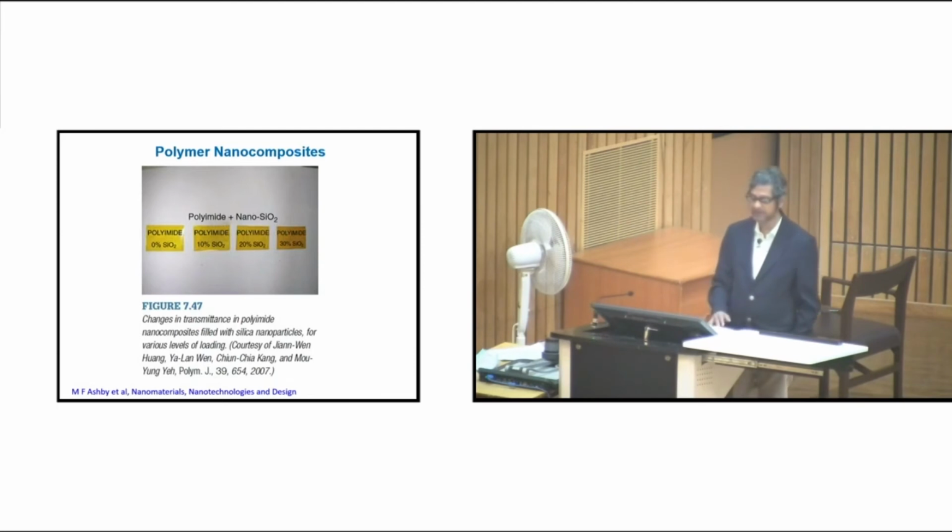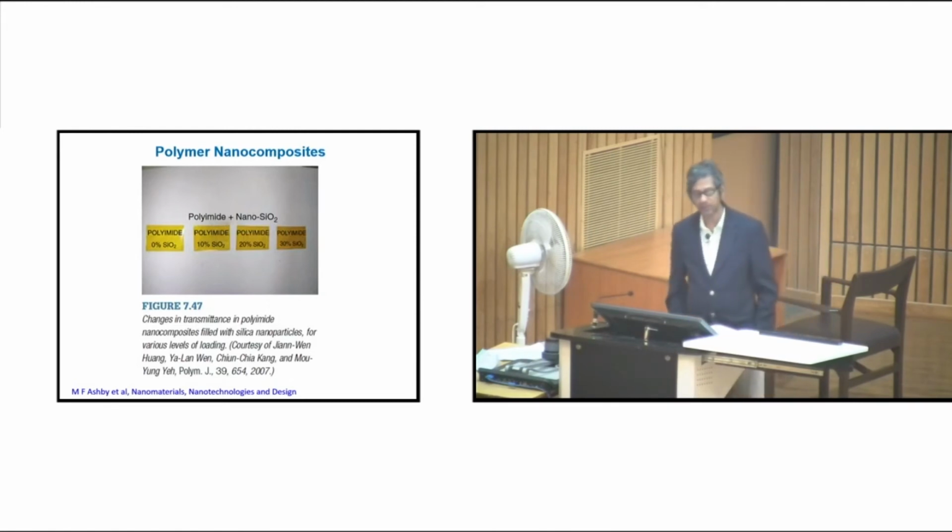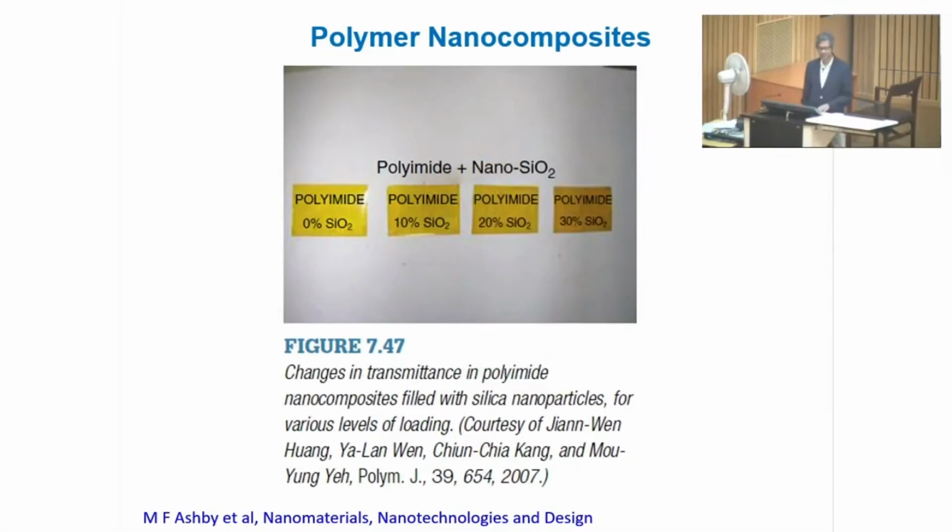To achieve transparency, the scattering must be minimized, which means the nanoparticles should be as small as possible, while the index of refraction of the matrix should remain as small as possible. For example, addition of nanoparticles of silicon dioxide to these things can control the transmission of the nanocomposites. Furthermore, the addition of nanoscale alumina to gelatin has improved total transmission by as much as 100%.